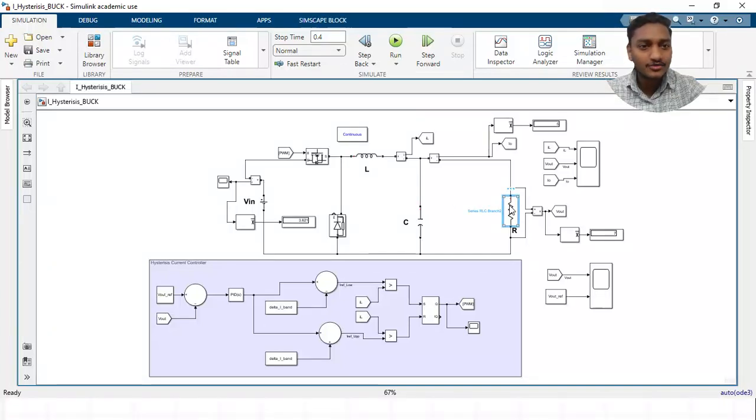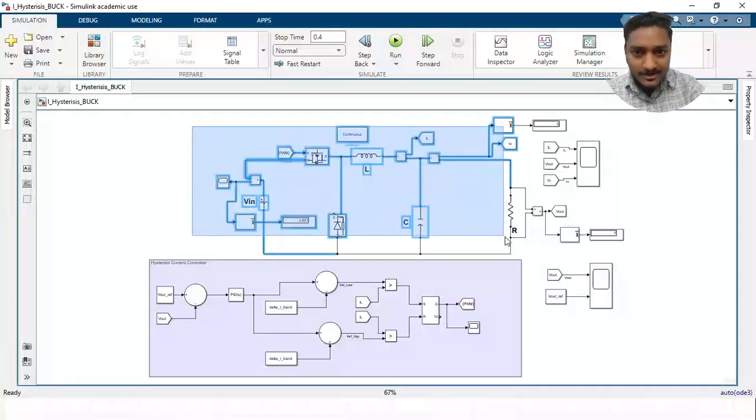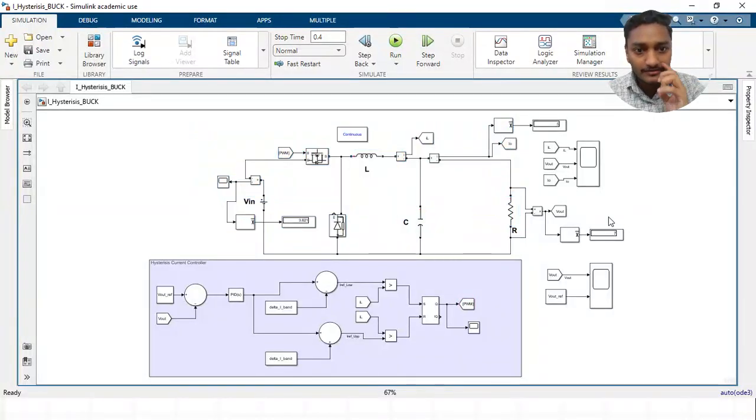Here in this case I am not applying the load transient because my load requirement is fixed. Now we will see the control block. This buck converter model you know already, and as I said, I am not applying the load transient here because my load requirement is fixed. In this particular case I want 7 volt as my constant output and 5 ampere as a constant current. That is why I am not changing the load here. I am keeping the load as actually calculated.